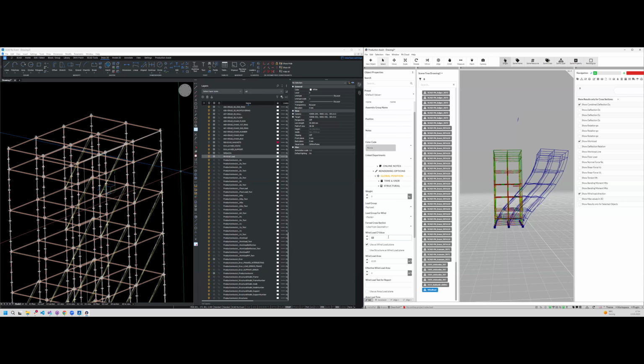Normally the CF value would be something like 1.3 for these things. Or if it's like a plane that actually lets the wind through, it could also be like 0.5. And then you see every time I'm doing this, it reduces the deflection and the pressure on the structure. So now, a long talk about this.